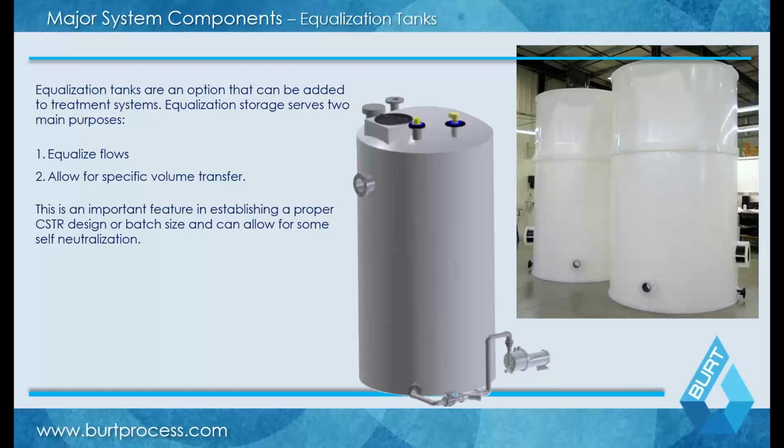It does offer a little bit of self-neutralization, but again, based on the pH scale, if one waste is 12 and one waste is 5, you're going to end up with mostly just 12 waste because of the logarithmic nature of pH. You need a lot of waste to get some kind of dilution effect going. So by and large, dilution is not the solution when it comes to pH neutralization systems.